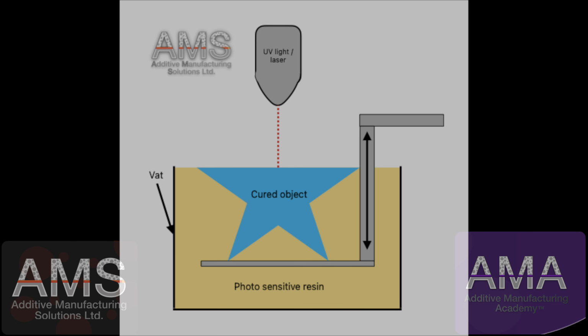The benefit of having a liquid bed rather than a powder bed is you can have a much more accurate and very nice finish to all of your parts. This technology has been used extensively in wind tunnel testing across space, aerospace and motorsport for many years and continues to be used as the number one technology to create wind tunnel models.